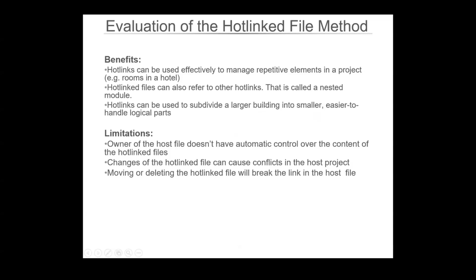A hotlink file can refer to other hotlinks, and using hotlink files too, what we can also do is, if you want some sort of reference to work to, you can actually hotlink, say, the main file back into your hotlink file so that you can work over it. And then when you export your hotlink to the main file, you can tell it to come into the main file without the nested hotlink. There's a little button to click that says include nested hotlinks or something like that. If you have that on, it will bring in all of the elements in your hotlink file. If you unclick that, it will leave out anything that you've hotlinked into your file as well.